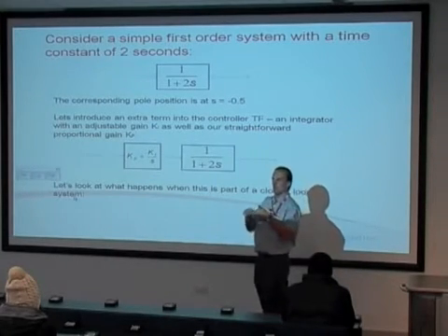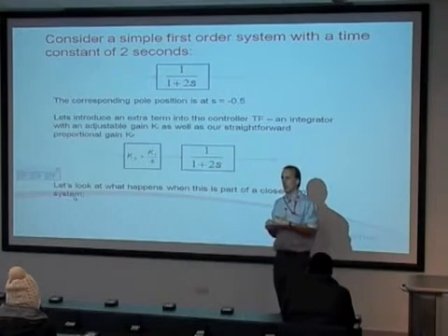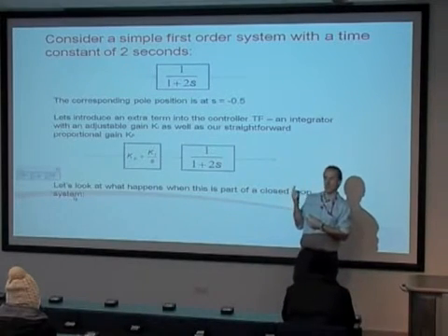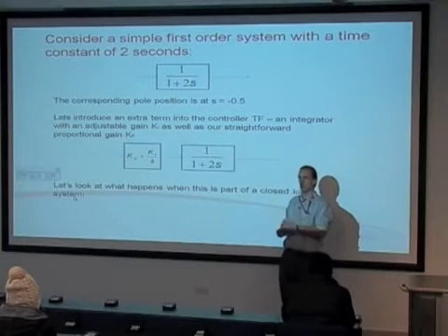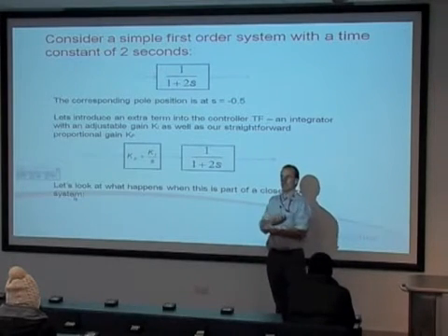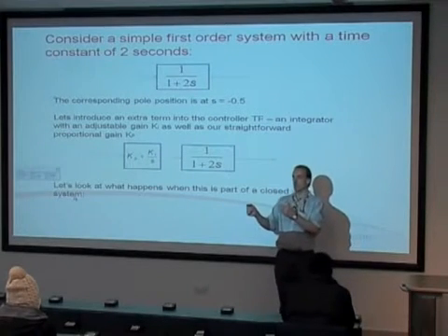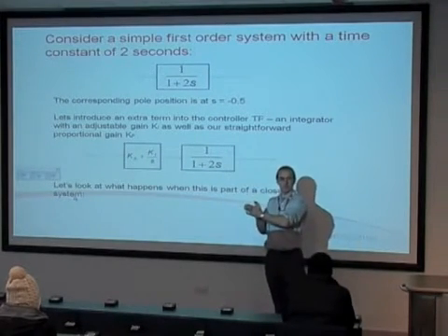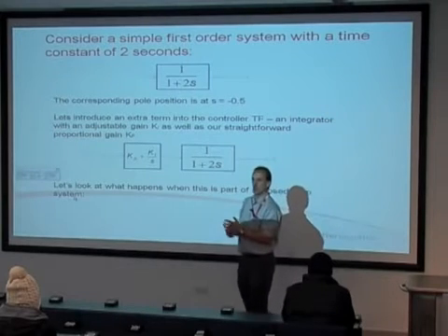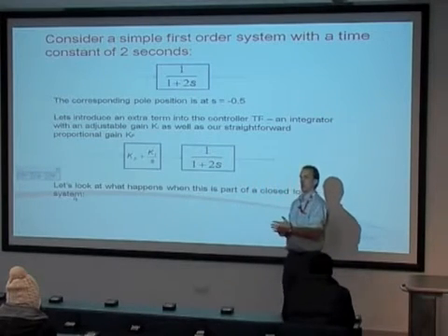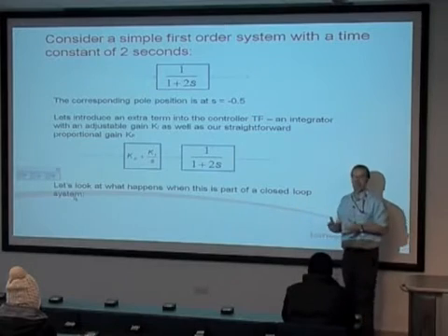If I just let it through without a gain, I've got 1 mile an hour's worth of push to open the throttle. If I put a gain in there, let's say times 10, I've got 10 times as much controlling effort to open the throttle. In other words, I open the throttle more quickly. So the response of the whole system speeds up.